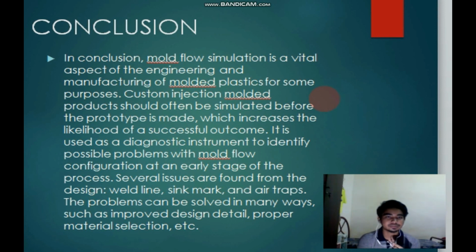It is used as a diagnostic instrument to identify possible problems with mold flow configuration at an early stage of the process. Several issues are found from the design, which are weld line, seam mark, and air trap. The problem can be solved in many ways, such as improved design detail, proper material selection, and so on. That's all.